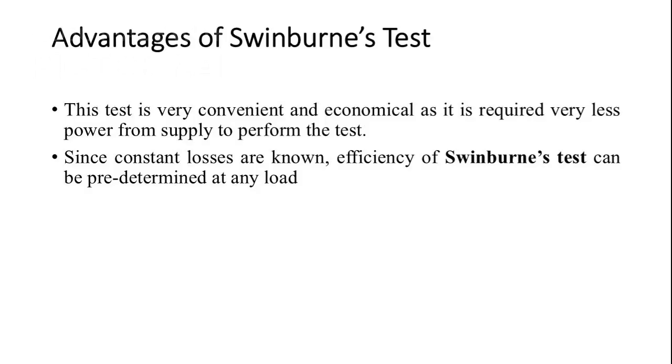Swinburne's test is convenient and economical as it requires minimal power from the supply. The efficiency can be predetermined at any load since constant losses are known.